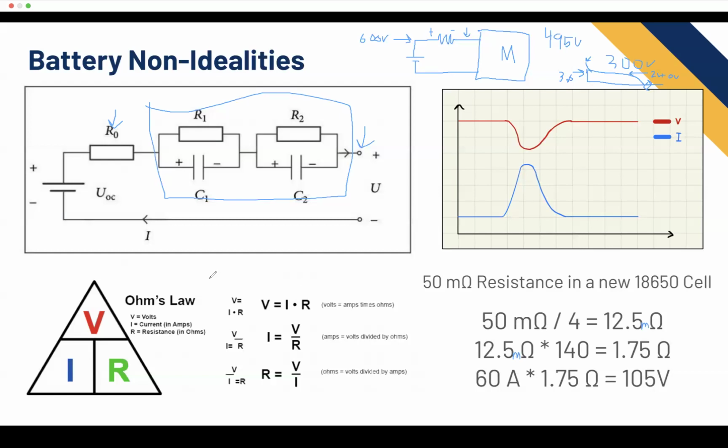Also, this isn't even getting into power equals I squared R. So this is how much your stuff will heat up, right? So if we're at 60 amps squared, so 3600 times 1 ohm of resistance, that's 3600 watts you're burning.